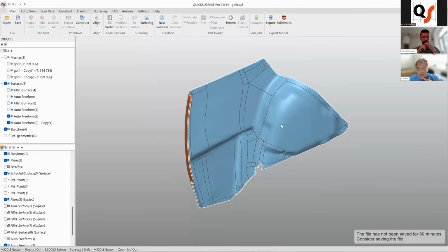One big mistake is that we always say, oh, I want to get the CAD model as close as possible to the scan data, if possible under 10 microns and so on. I had an argument in one of the groups. They said, how accurate is your algorithm? We can make it as accurate as you want. Like Viktor shows you, you just press the button, increase resolution, and we can get under 1 micron. But how useful is this data? This is the most important question. So it's really in your hands.